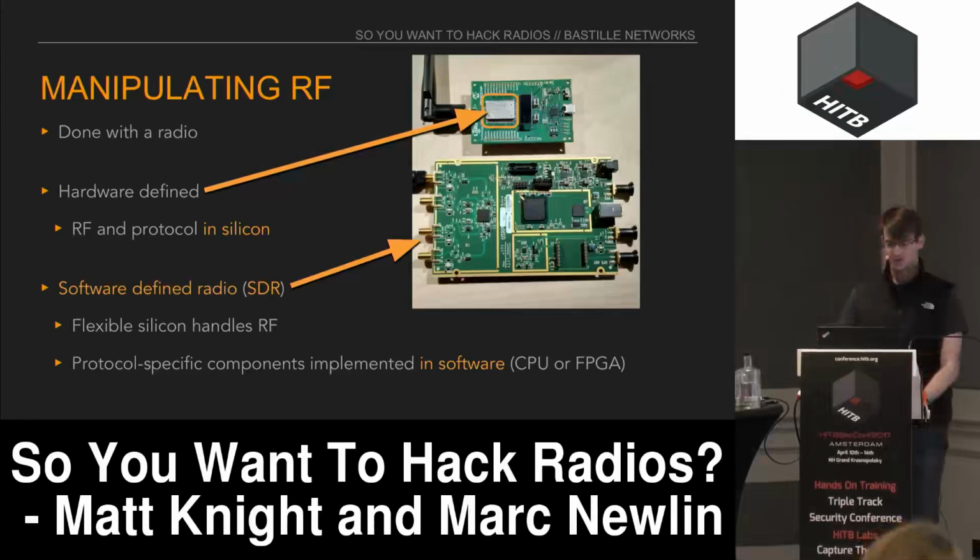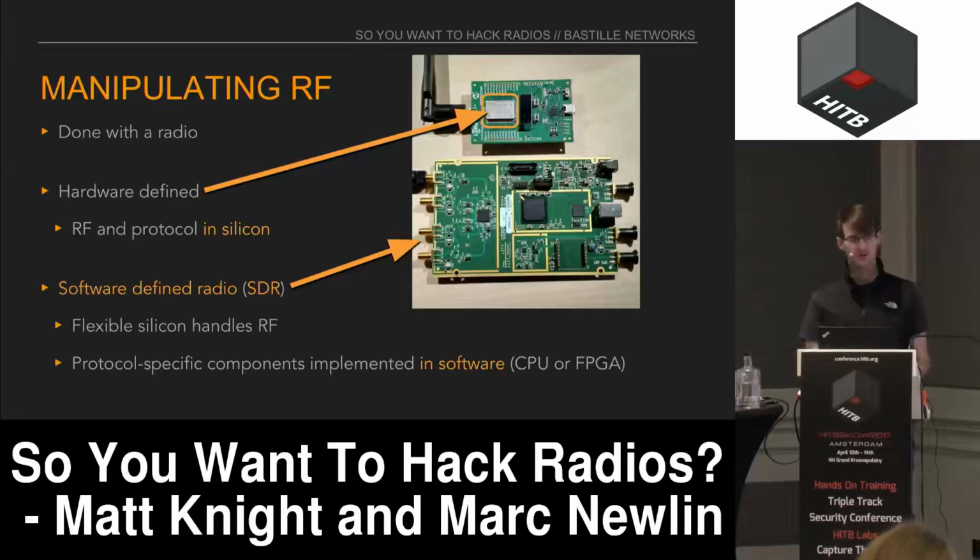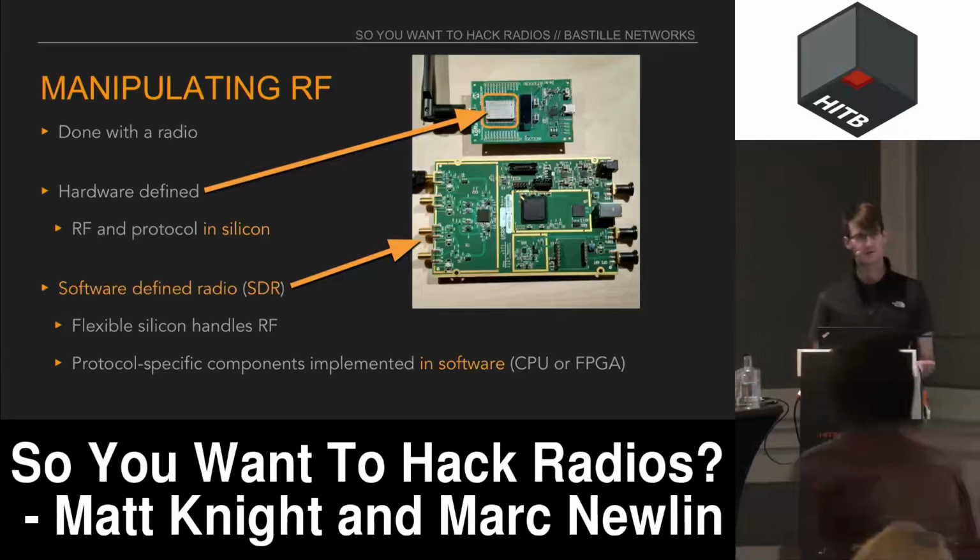So you can manipulate RF by using a device called a radio. And as Marc mentioned, radios can either be hardware-defined, as is the case with the LoRa radio shown on top there, or they can be software-defined. With the hardware-defined radio, again, the features are baked into silicon and are not flexible. With software-defined radio, it's really just a way of grabbing raw radio information and passing it off to some sort of reprogrammable logic, whether it's software on a host or configuration of an FPGA.